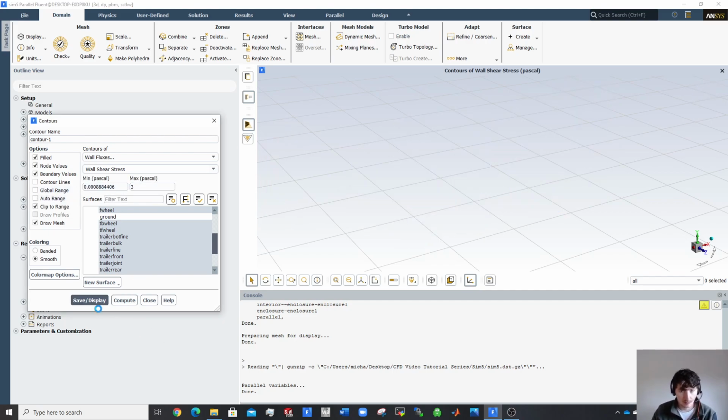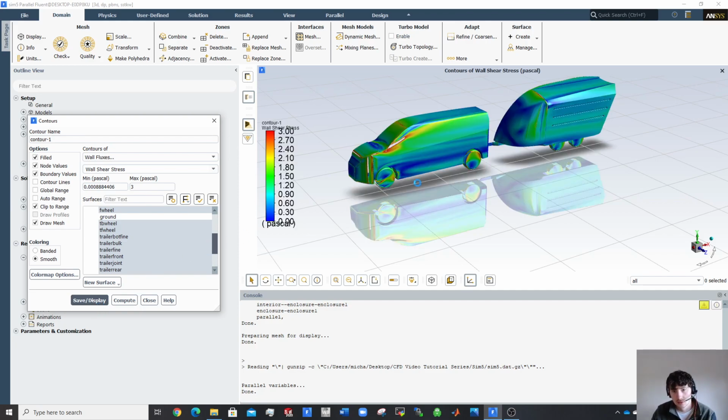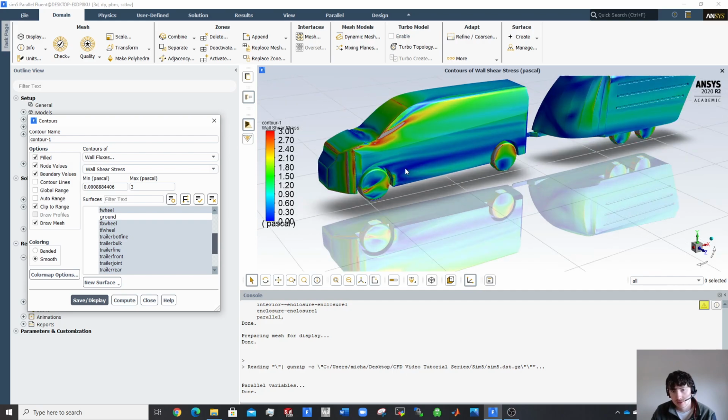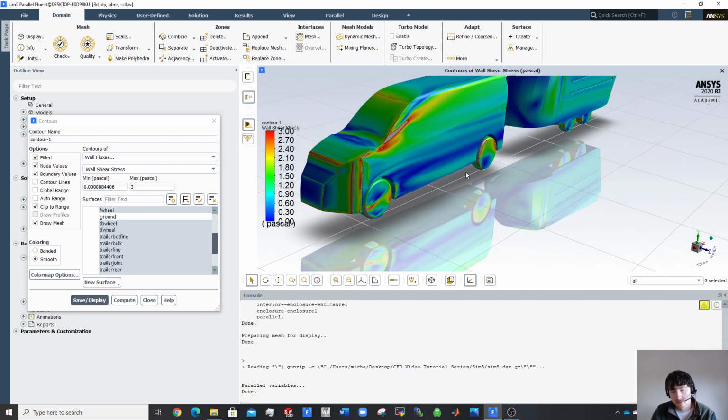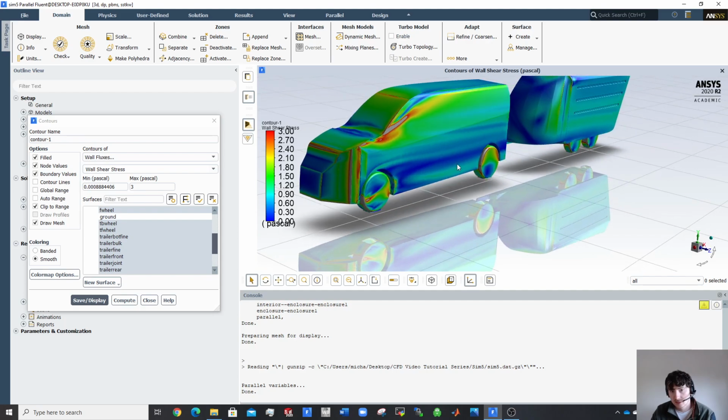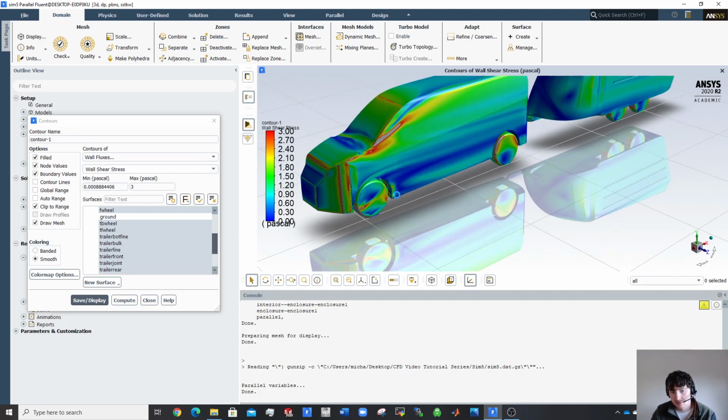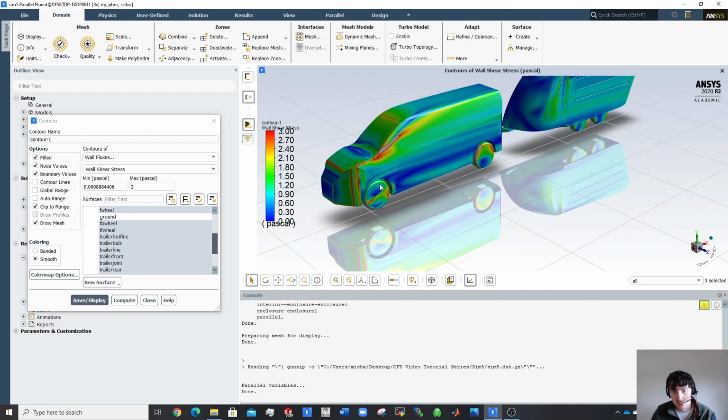Let's see what this gives me. Okay, so this is giving me more information now, right? This is showing me that dark blue would signify that the flow isn't really attached to the vehicle. So I can see along there, as the wheel is spinning, the flow detaches here. It usually does detach, comes over that, and I find it very difficult to stay attached early on, but then it might reattach as it moves down further. But usually along there, it's quite typical that you'll see the flow not attached.